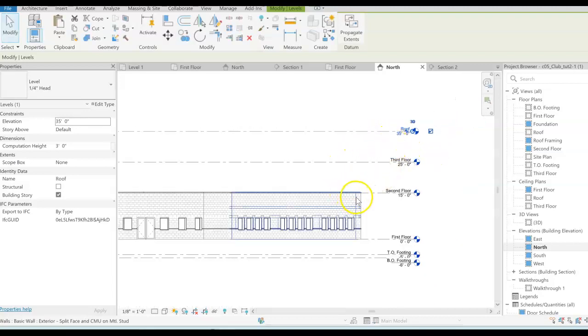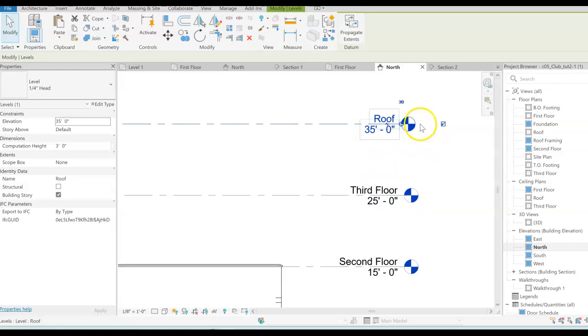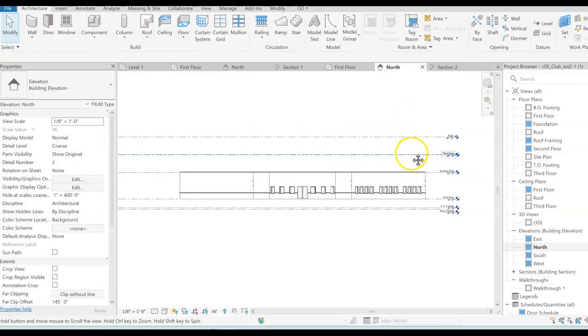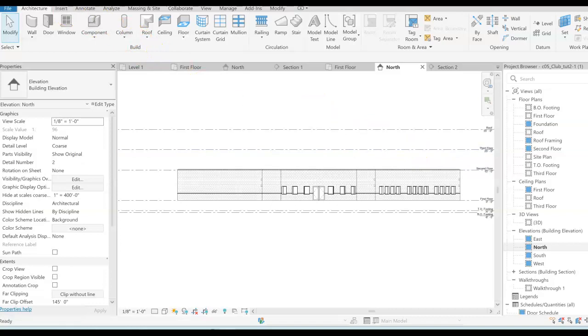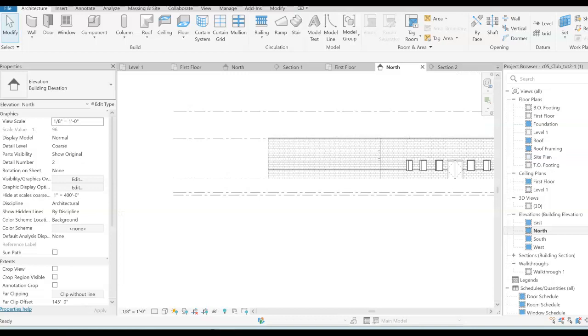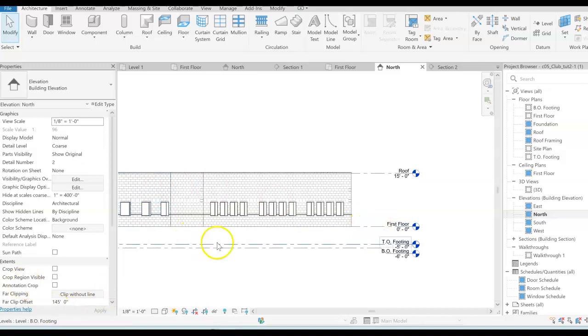So this would allow me to make a wall and say send it to the roof, right? Top of roof. And so that wall could be increased. And I can put my floor plates. So that's what I would do if I wanted to create more levels. But that's not the object here. So we'll undo this and go back to last known good piece. There. And this would conclude this particular tutorial.